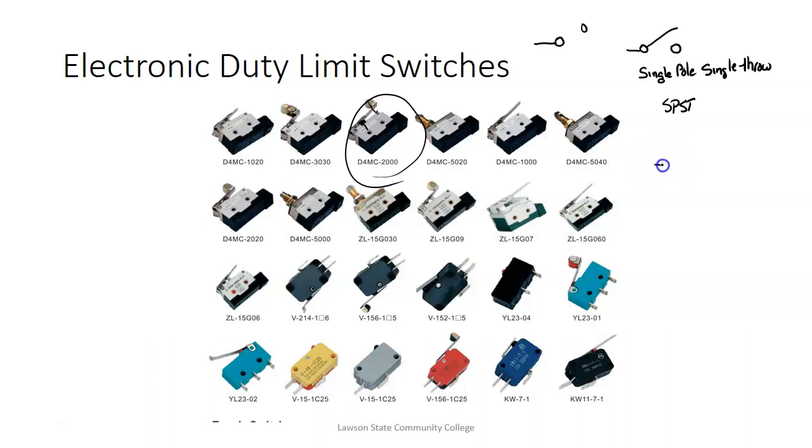If we come over and do this, this is what we have that controls lights. So here we have one switch control that we can put in two different positions. This would be called a single pole double throw, SPDT. This is the one they use. By the way, electricians don't call it a single pole double throw. They call it a three-wire switch, or three-way. They call it a three-way switch because it's got three wires connected to it. I guess that's how it got the name. But these are single pole double throws.